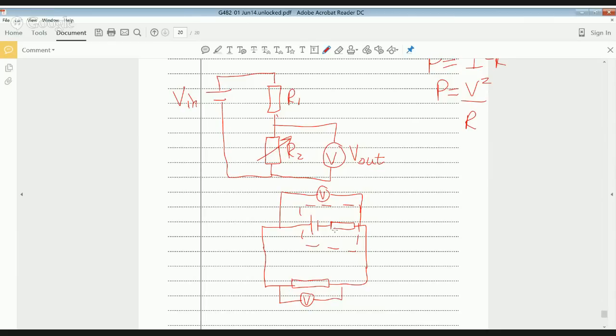Monaco Super, I'm assuming you're referring to the second question with the circuit there, asking how you get 0.08 amps. The 0.08 amps is calculated because we know that the current at point X is 0.16 amps, and part 3 of that question tells us that the current at X is twice the current at Y or Z. So we know the current flowing through Y and Z is half that, so that's the 0.08.